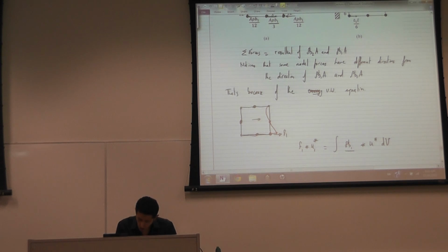I have a force here, rho B1, distributed, and I want the equivalent force on node 1. The equivalent force that would produce the same virtual work. It turns out that this is negative. The work done by this distributed load during the application of this displacement is negative.